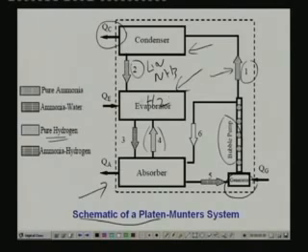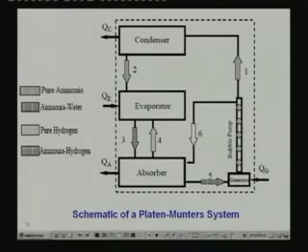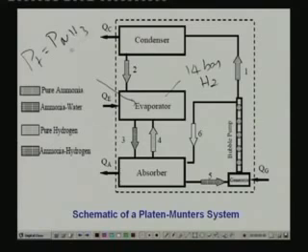In fact, this pure hydrogen makes up most of the pressure in the evaporator. Since total pressure is the same, for example, the pressure at this point is, let us say, 15 bar. So, 15 bar liquid is entering the evaporator, and inside the evaporator the partial pressure of hydrogen is 14 bar, let us say. So, 14 bar is because of hydrogen. What will be the pressure of ammonia here? It has to be the partial pressure of ammonia, because the total pressure is constant. In the evaporator section, P total is equal to P ammonia plus P hydrogen, and P total, as we have seen, is equal to 15 bar, and out of this 15 bar hydrogen makes up 14 bar. That means the partial pressure of ammonia has to be 1 bar.